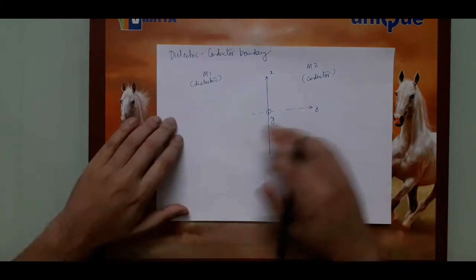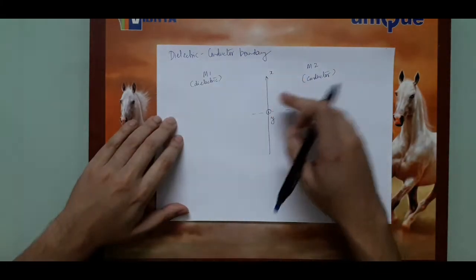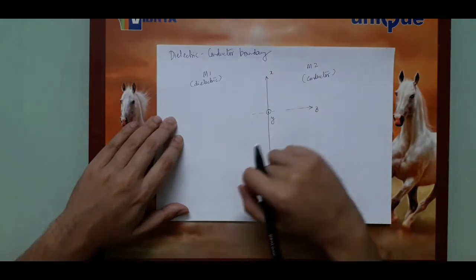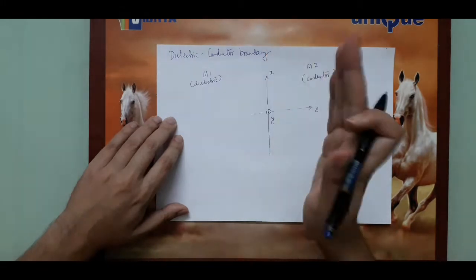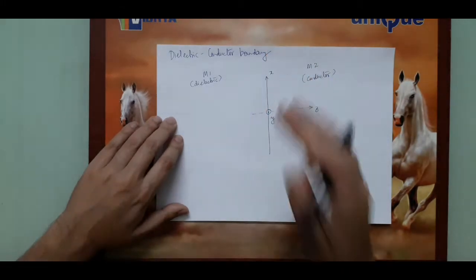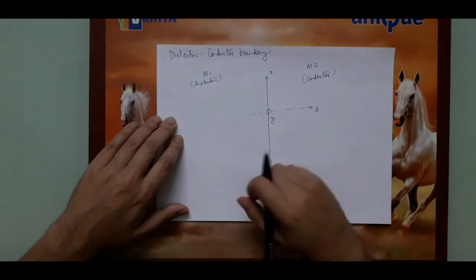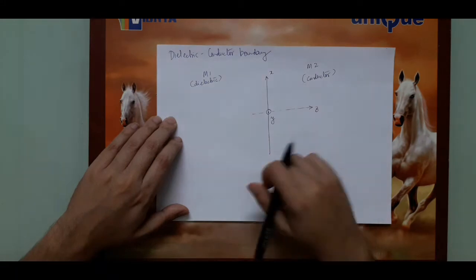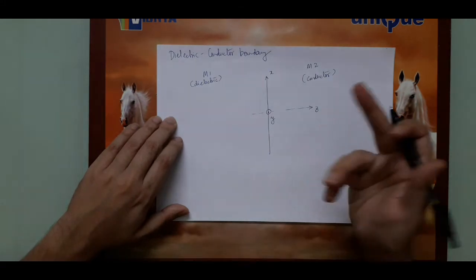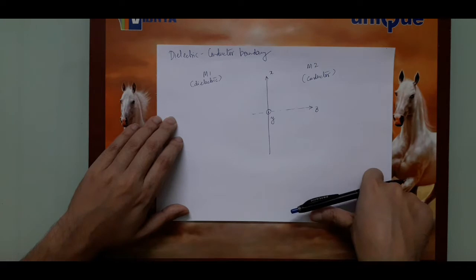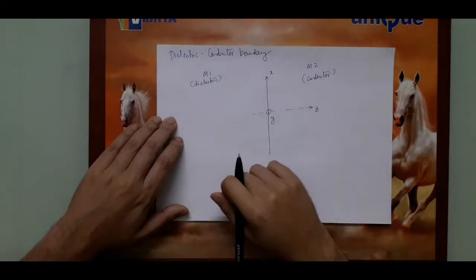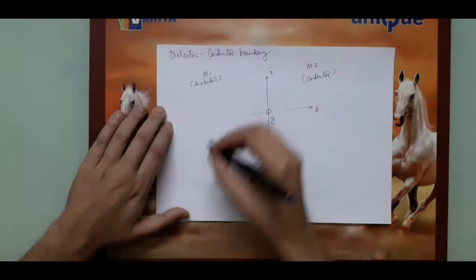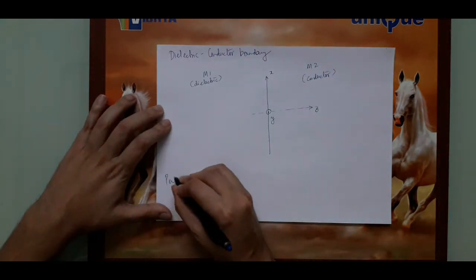As per boundary conditions, we know that the waves will not lie deep inside the conductor, rather they will mostly exist along the surface, and inside the conductor body, the waves will either die out very easily, or they will exist in the form of either surface charge or surface current, something of that kind. In fact, both can also be possible. So let us consider the case of the perpendicular or the vertical polarization.